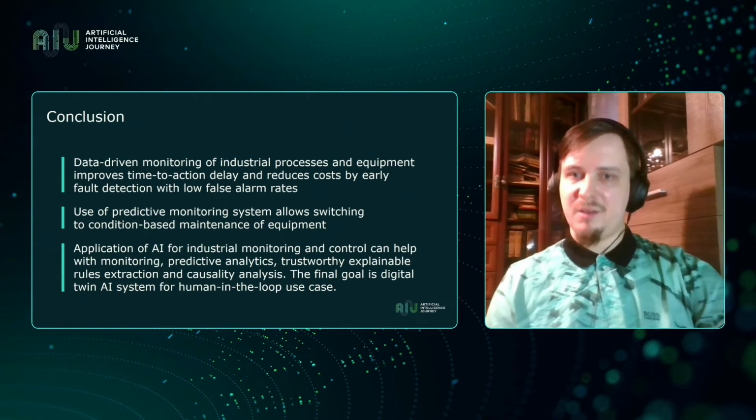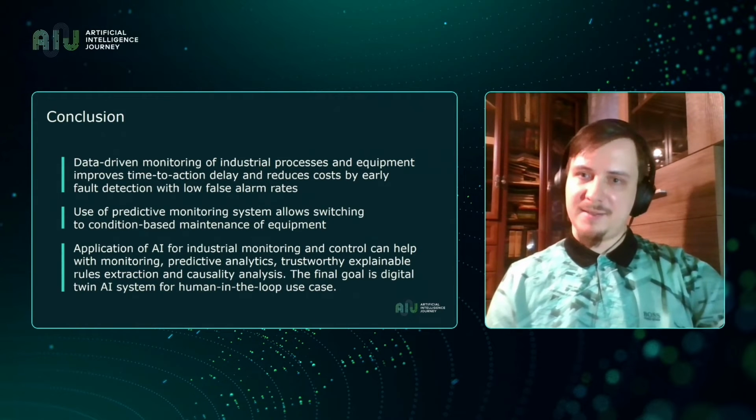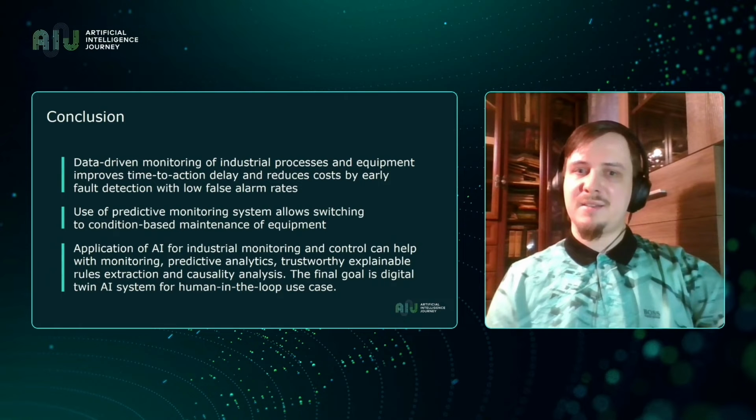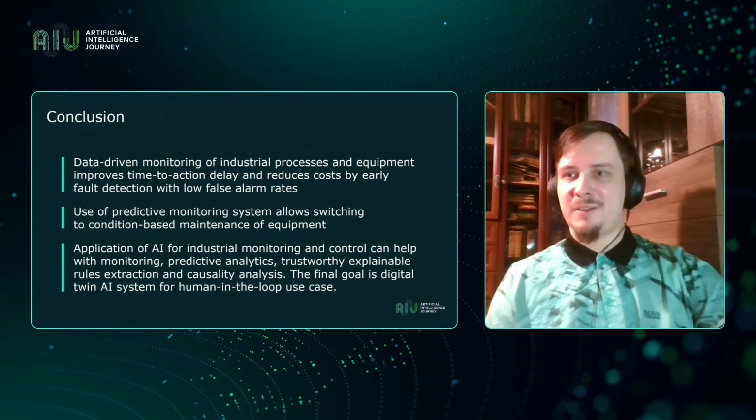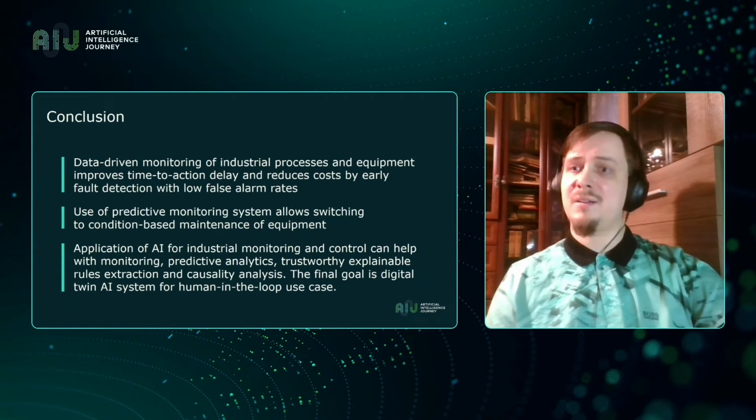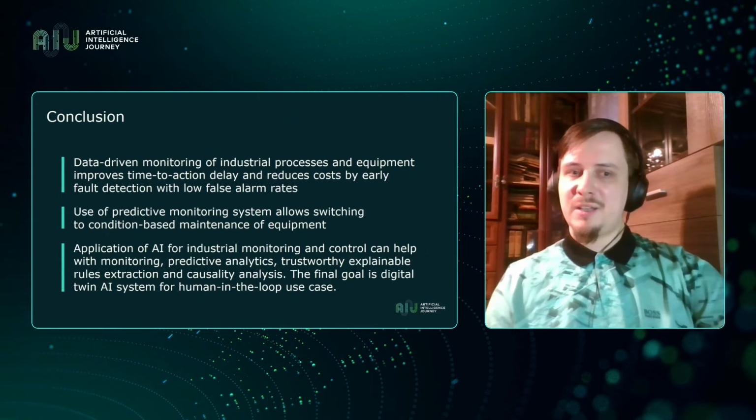When you're observing the machine, when you're detecting the dynamic of its depreciation, you can predict its condition more accurately based on the current condition of this equipment, based on the data that we receive from multiple sensors on this equipment. And we also can take into account that some sensors have broken down and some sensors are not simultaneous in terms of the way they're providing their data.